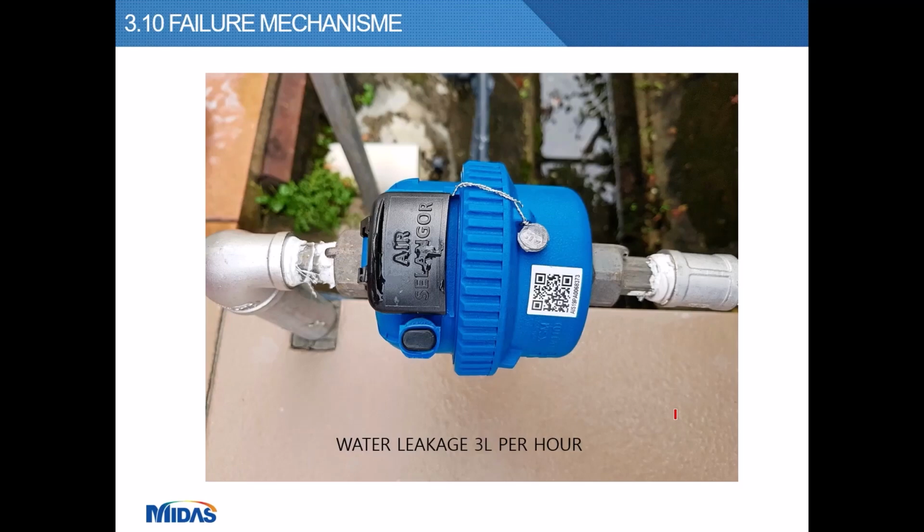And we think that possibly the failure could be caused by the leakage, as the moisture content of the fill after the failure was as high as 40%, while the surrounding exposed fill was actually dry. And we will verify our hypothesis by numerical modeling.